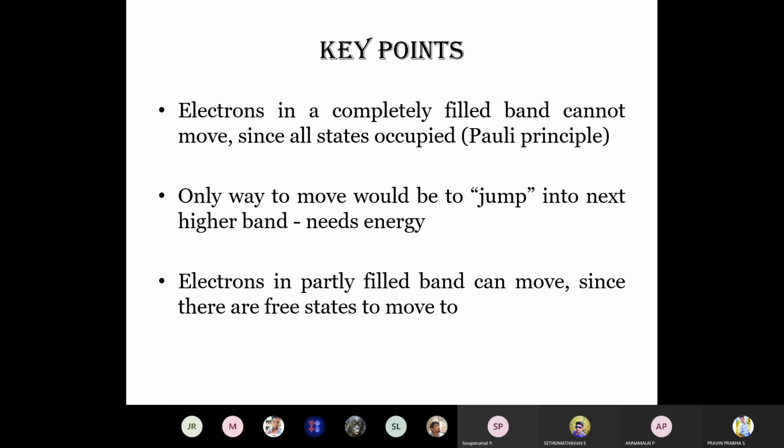So here, when we discuss electrons and holes, a completely filled band cannot move. Normally electrons cannot move since all states are occupied, like the Pauli principle. So the only way to move would be to jump into the next higher band, which needs some energy. A partially filled band can move since there are free states to move to.